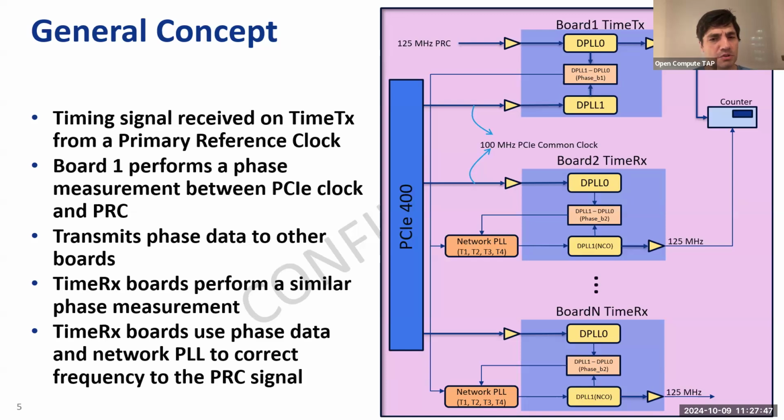So spread spectrum is a requirement for what Julian is doing. Is that correct? Like on the PFM? Correct. Yeah, you have to include spread spectrum. It's commonly enabled, and it's enabled at the host, and it's not in the motherboards that we were dealing with. There was a handful of motherboards that had spread spectrum. A lot of them didn't, and these were like consumer grade motherboards, right?